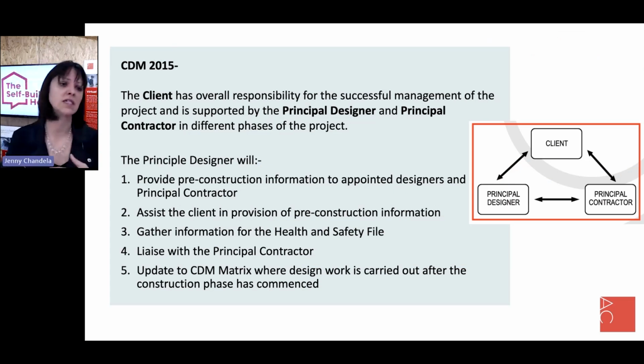I mentioned CDM 2015 and principal designers. So you as the client can fulfill these roles. However, we as the architects have PI coverage. We're regularly dealing with these processes, so we have the experience to know what really is required for these regulations and for compliance. So typically, we will fulfill that role of principal designer, and then that role will be handed over to whoever is acting as the principal contractor. Once again, that is a role that you can fulfill, but just make sure that you are very aware of what these CDM regulations are and how you fulfill those as either a principal designer or a principal contractor or both.